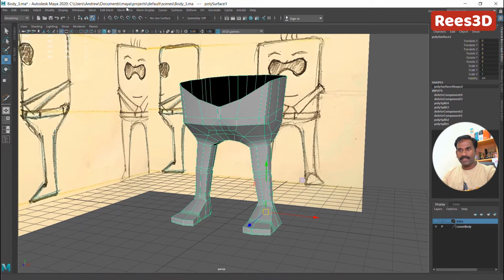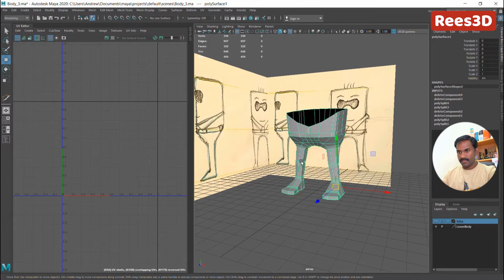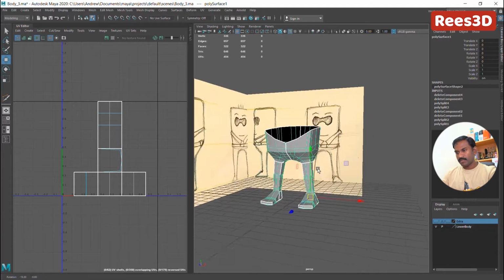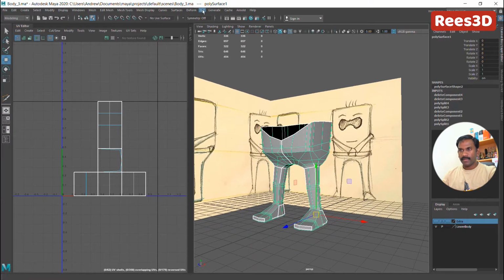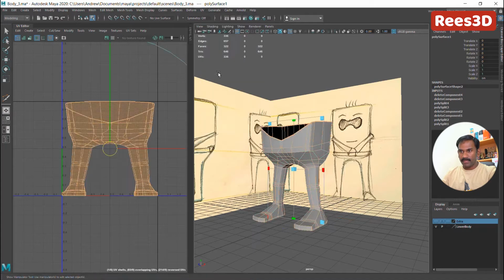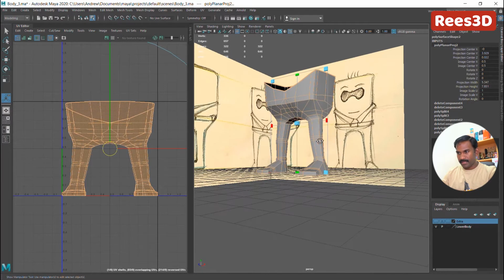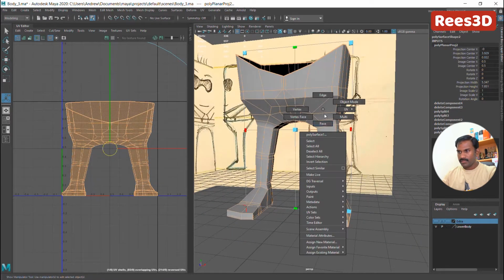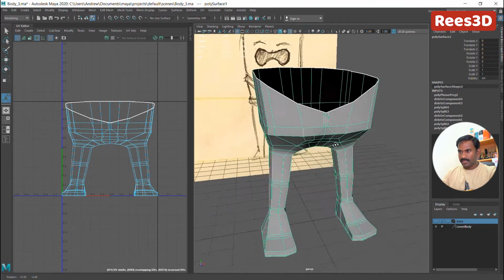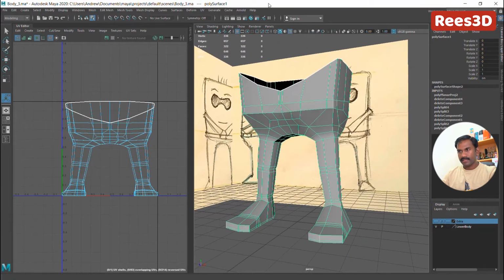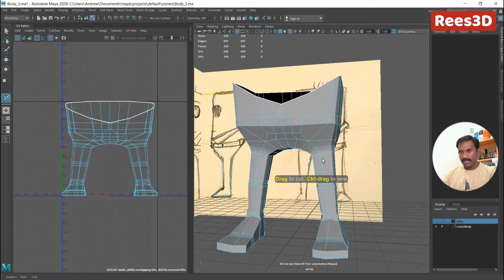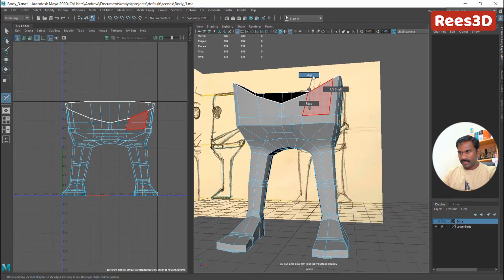So let's go ahead and check out our UV editor. Click on that, select the object, and that's the UV that we have. So again, as we did earlier, I'm just going to apply a UV planar mapping here. So that's just going to do that. And now we will actually start splitting this into different sections. So what I want to do here is take the UV and 3D cut and sew UV tool, and then we need to make sure that we're in the edge mode.